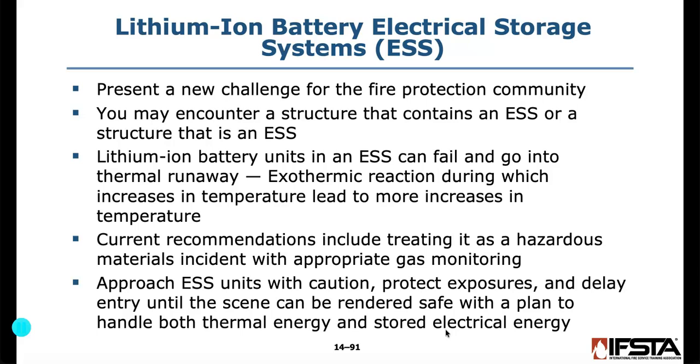You could try to cool it, but really what you need to do is get it away from the other battery packs, or the other banks of batteries, because that heat from the one in thermal runaway will then cause the others to go into thermal runaway, and that's where you have a big problem. Current recommendations include treating it as a hazardous materials incident.